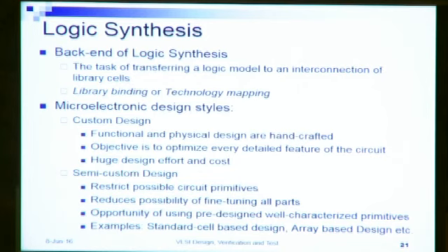So you can pre-design these units, optimize them to the best extent possible, and then use them. So the trade-off is that you cannot optimize with respect to the last transistor possible. However, you can handle much bigger designs and you can optimize across these primitives.